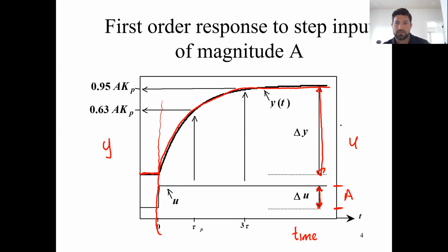One thing we already talked about is what gain is. Gain, Kp, equals delta y over delta u, or delta y over a, because delta u is equal to a. This is given from the transfer function. So if we're given a first order transfer function, we know what the overall new value is going to be in response to the step change to the input. Now, in terms of plotting this, we can plot the initial value, and then some value over here as time approaches infinity.